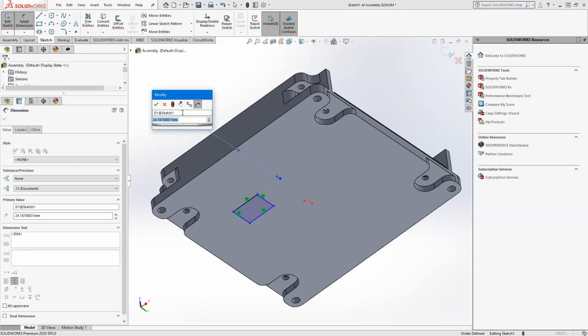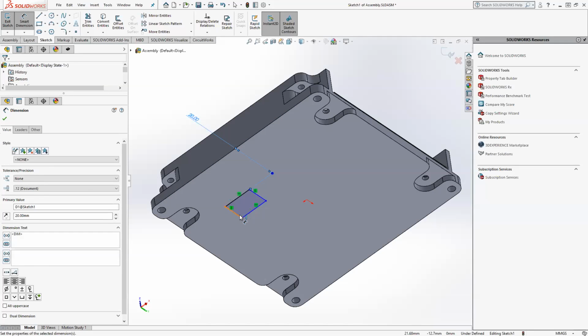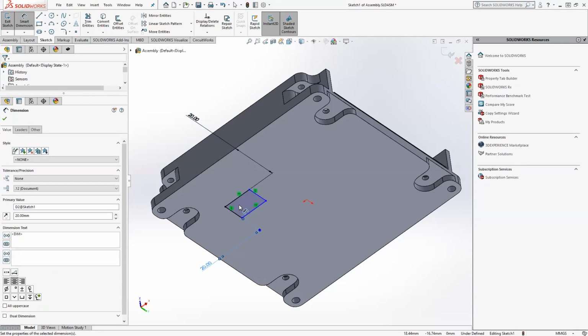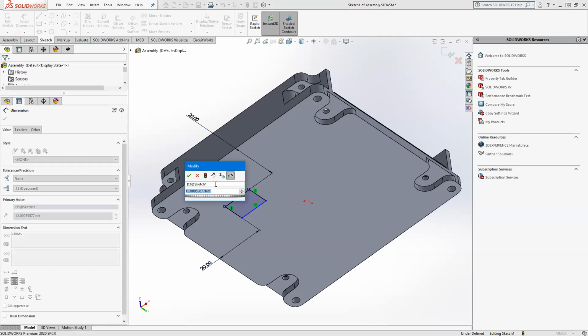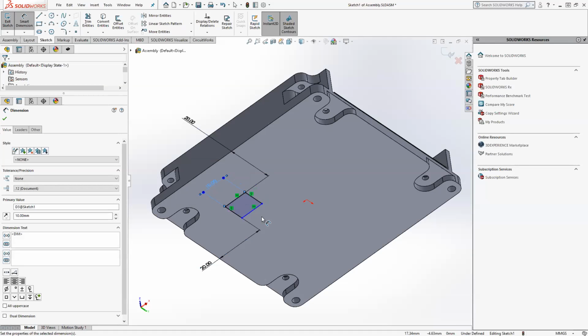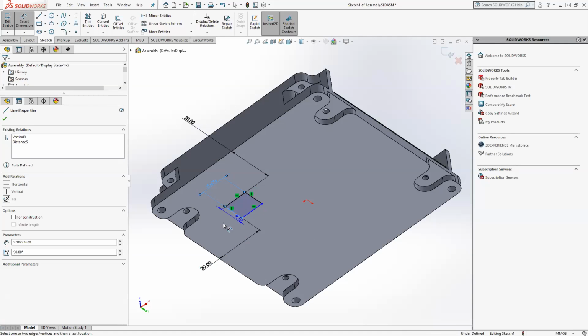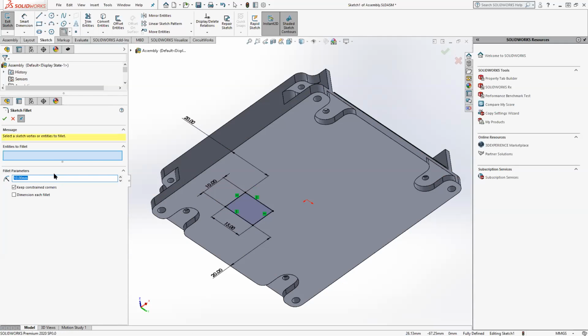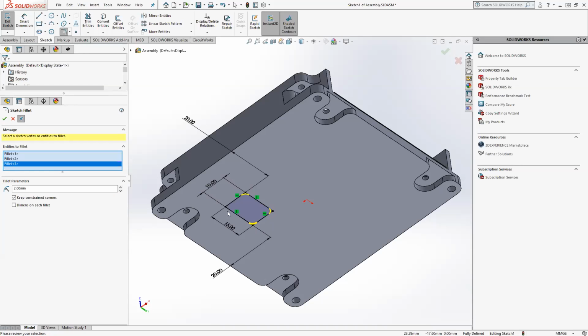Let's say 20 millimeters from this edge, 20 millimeters from this edge, and make it, say, 10 millimeters by 15 millimeters. Obviously, you couldn't actually create a cut with these sharp corners. So let me just put a couple of, say, 2 millimeter fillets in these corners to make it something that could actually be manufactured.